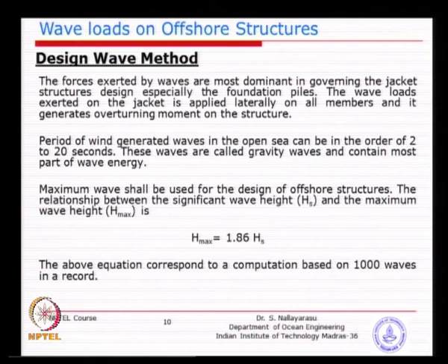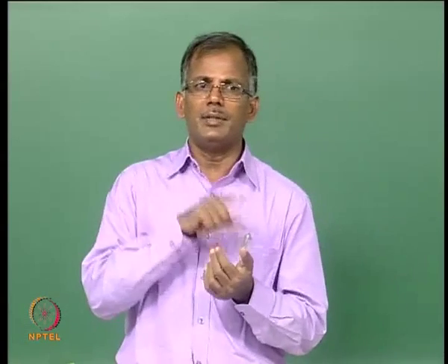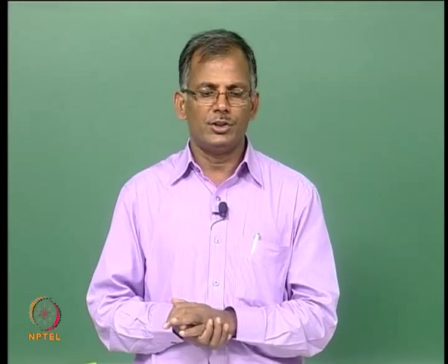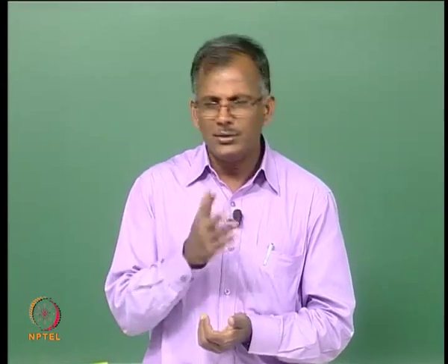You go to any place, the wave period, the time difference between the successive crest or the trough, is typically between 2 seconds to 20 seconds. Sometimes you get less than that. Most of the places you get a maximum of 12 or 14 seconds, but 20 seconds is almost like a tsunami. Basically, almost no trough will be there.